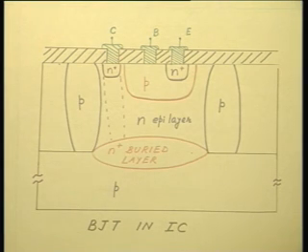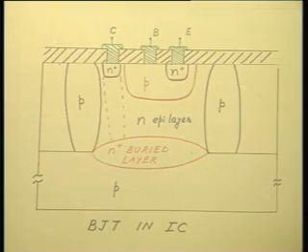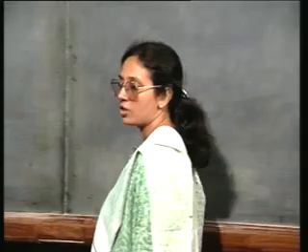Okay. So, this is, as I said, a comparatively older bipolar junction transistor which uses junction isolation. Junction isolation, that is, this reverse biased PN junction is used as the method of isolation. Okay. Now, let us look at this junction isolation technology, because immediately after buried layer we must concern ourselves with the isolation and the junction isolation.